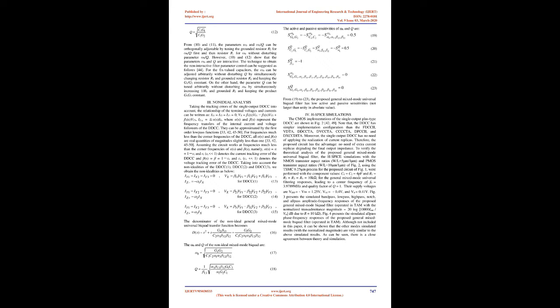Using standard notation, the port relations of a DDCC can be characterized by IY1 = IY2 = IY3 = 0, VX = VY1 - VY2 + VY3, IZ+ = +IX and IZ- = -IX. The current output has very high output impedance.